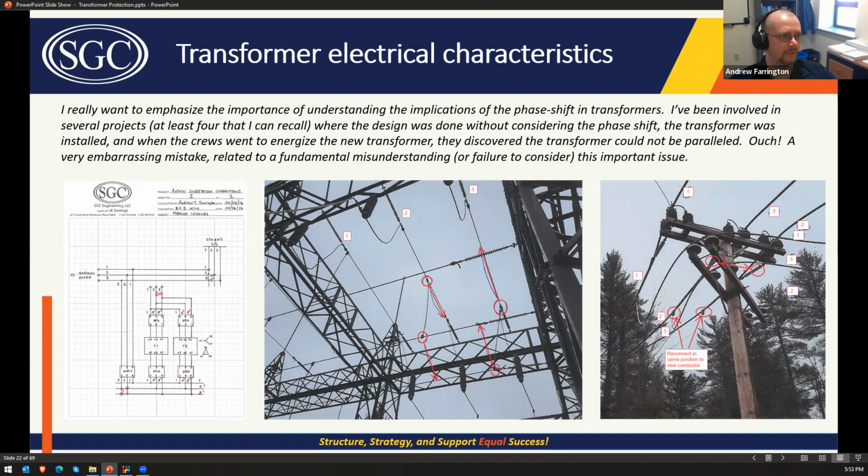So Bill Wise and I walked to the substation that was owned by the local utility, and then we walked the right of way because they had the phases marked and we could see it from the road. We took a picture of what the phases were, and then we walked the substation to see if there were any phase rolls. Then we traced it back to the municipality substation and identified that their 150 to 34 transformer had a different phase connection than the utility's, and that's why they couldn't phase.